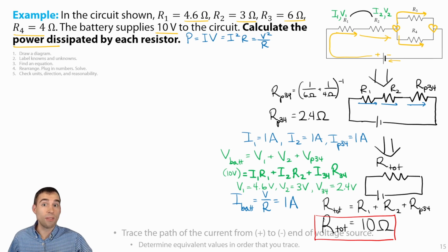And now we know that the voltage from resistor 3 and 4 being in parallel with each other will be the same at the beginning and end points of that parallel path. The voltage at the first node will be equal to the voltage at the second node. The current might not be the same across each path, but we can figure that out.